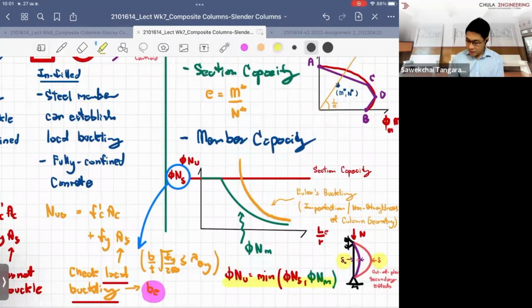But in the concrete design, we don't have this adjustment for the member capacity, because when the concrete is taking the compression force, it favors the concrete material, because concrete can take compression well. Concrete doesn't like tension. Steel is favorable for tension force, but it doesn't do well if we use it to take the compression force, because the steel is so thin compared with its geometry.